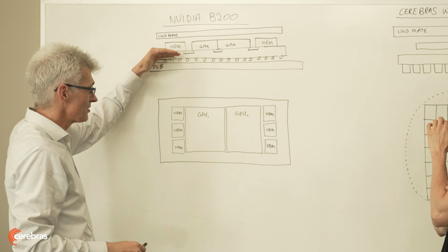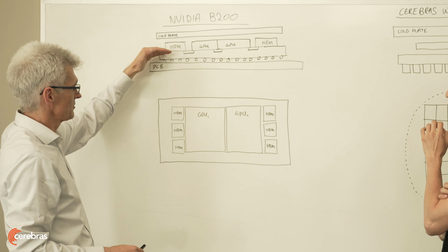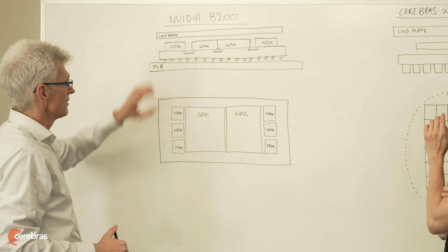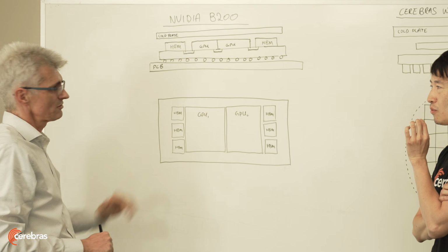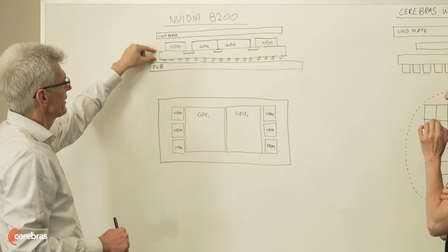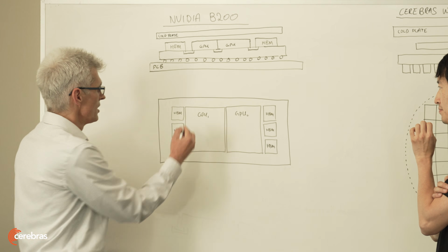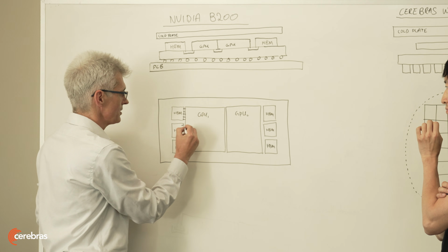So sometimes they put a silicon interposer on a package and then on the printed circuit board. Sometimes it's directly stacked as it is shown here. So let's simplify it and just say this is a silicon interposer, and you have multiple die that you need to interconnect between each other. So connectivity between the HBM and the die.